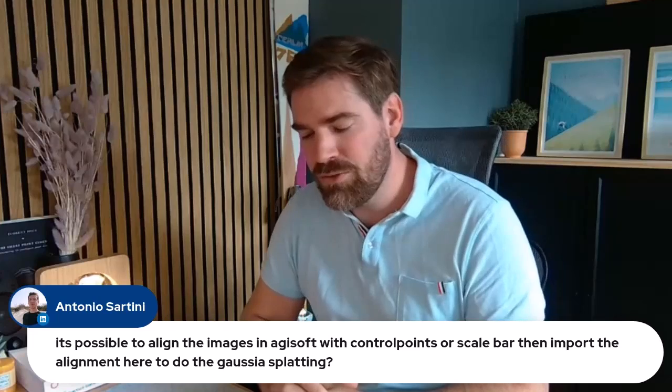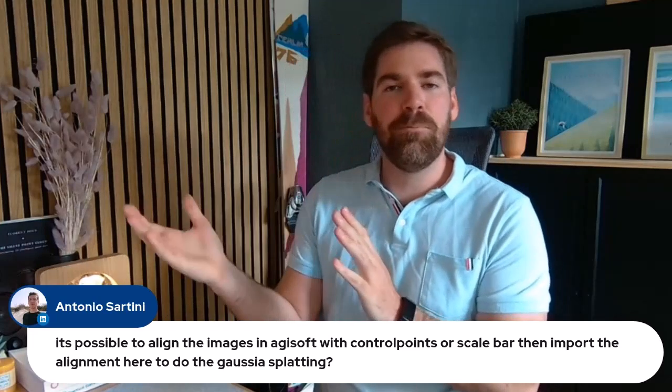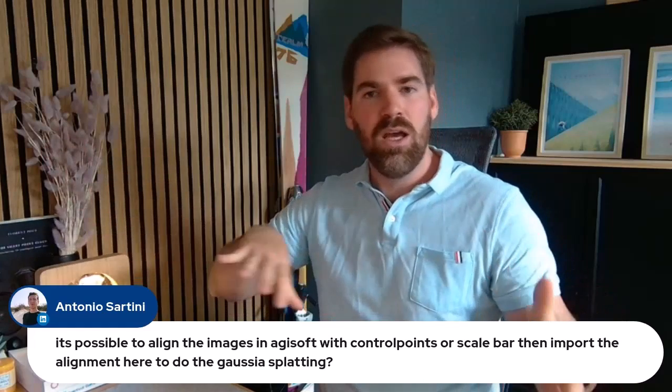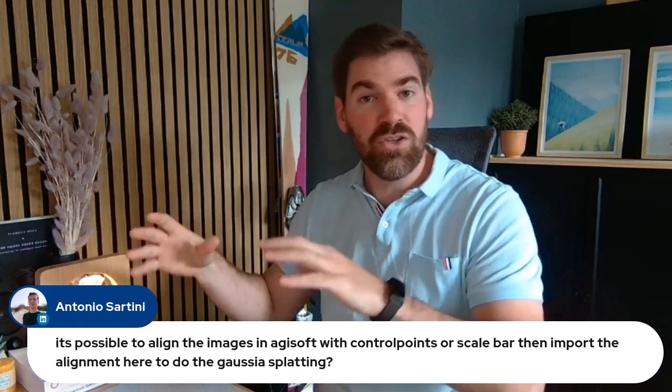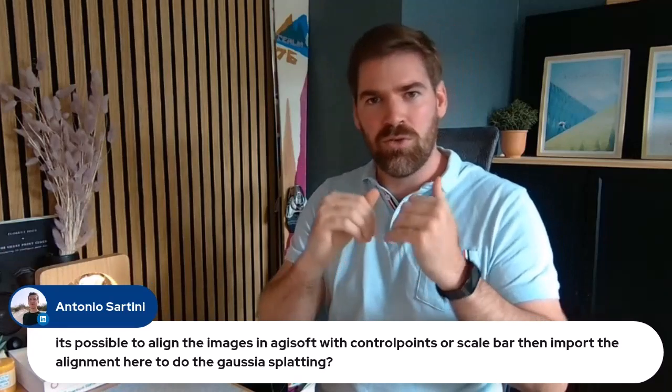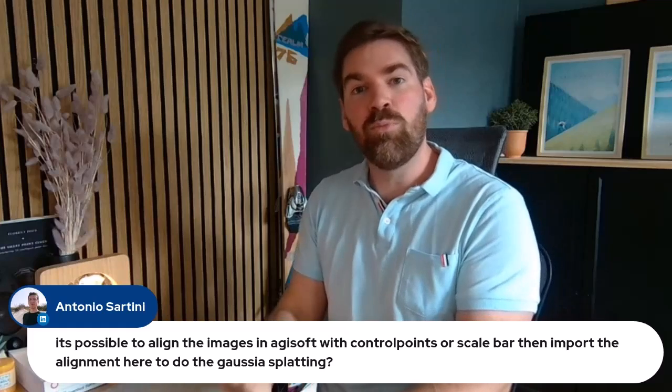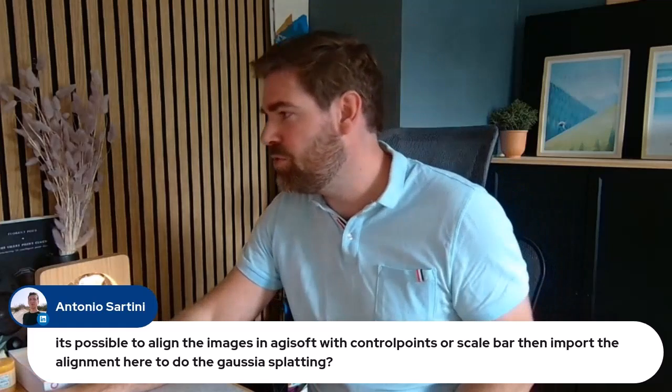What I always advise is splitting up what you use as control points after the adjustment, so basically just a rigid transformation, and what you use within to also do some kind of deformation. You need both, and you also need control points to assess the accuracy of your reconstruction.